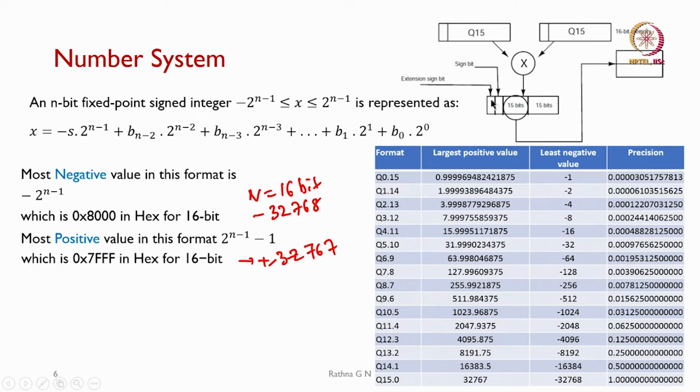So, we call this an extension of the sign bit, and we will be discarding this, and then we will be taking the 15 bits, that is the MSB bits from our output, and storing them in the memory. This we call truncation. So, if I know that most of the values are in these higher 16 bits, then I can do the truncation.